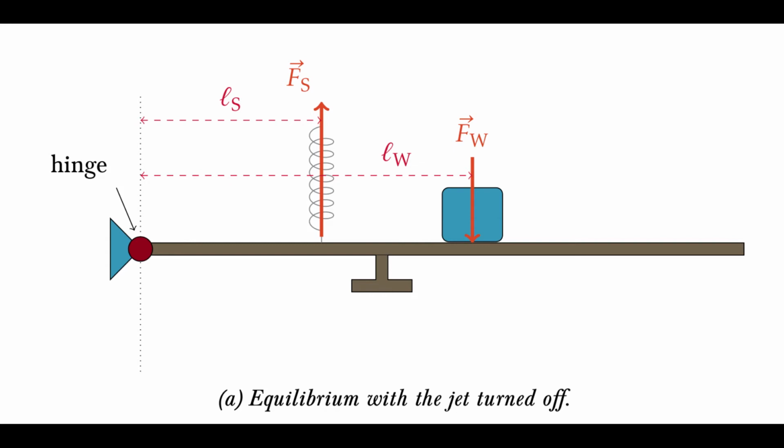The experiment will then be repeated again for a different flow rate. This means the valve will be turned in order to produce a different flow out of the nozzle. The mass will then have to be moved again and its distance recorded. After which, the mass flow rate using the counterweight system will need to be measured again. The procedure is then repeated again for a hemispherical cup instead of a flat plate.